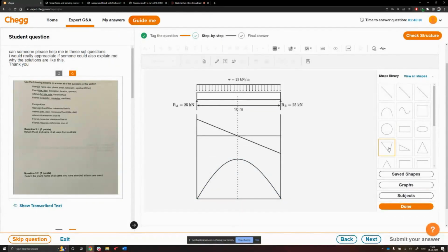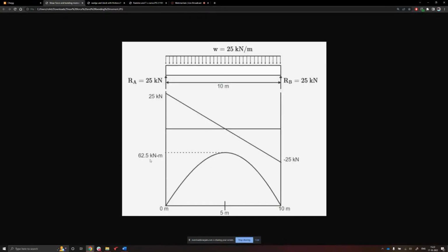like this. Now you would want to add text on the shear force diagram and bending moment diagram, something like 25 kilonewtons. And you can always use the copy paste tool, move it here, use the arrow keys to move it at the specified location, and this will be minus 25. And then the same way you can add more text to the bending moment diagram also.